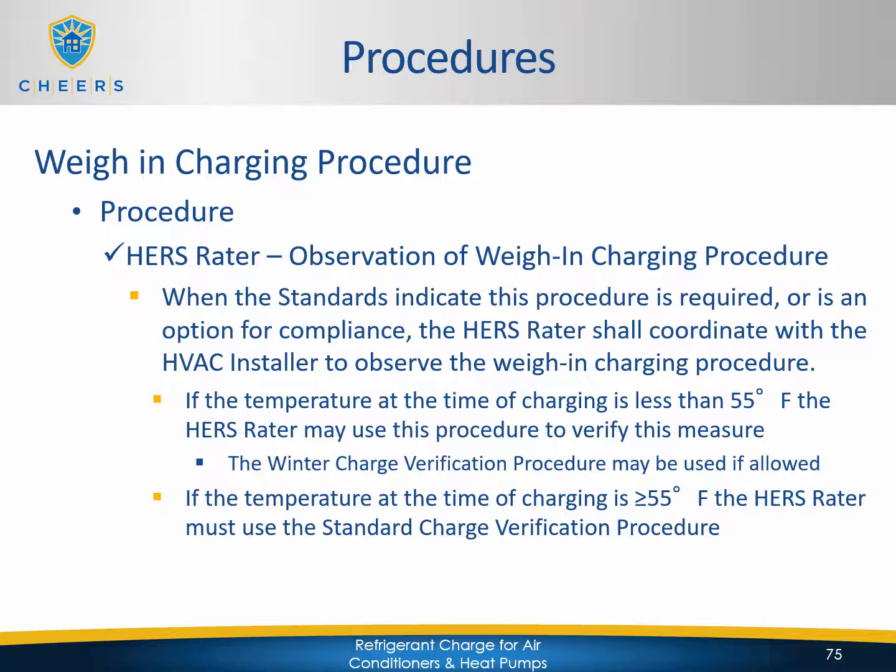The second option is if the temperature at the time of your charging is equal to or greater than 55 degrees, then you must use the standard charge verification procedure. The other option is if it was weighed in at a time when it was less than 55 degrees, the HERS rater can come back at a later date when the temperature does get into the range for the standard charge procedure and perform that standard charge verification procedure.